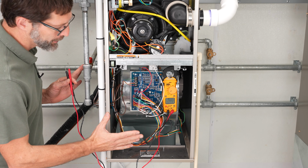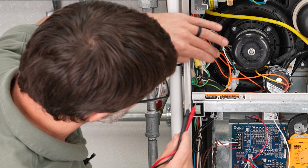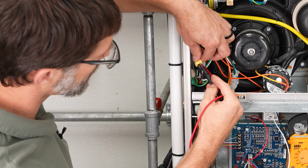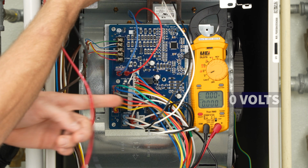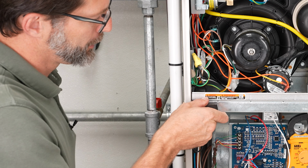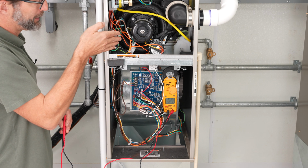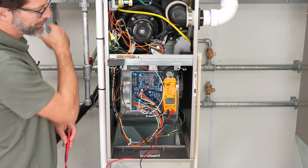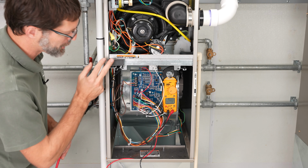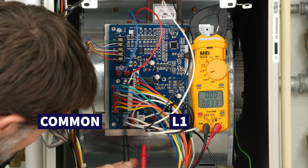If we think we have power onto the furnace and there's still not an LED status code light, what we can do is take our measurements right up here for voltage and alternating current, and we see that we're measuring 0 volts. Now, the other thing is we want to close the door switch if we're going to measure down here. Of course, we've already measured 0 volts, so that means that anything upstream of it is going to be the problem and not downstream. If we measured 120 volts here, then we could close the door switch and then come down here to the L1 and common neutral bar and measure down here.